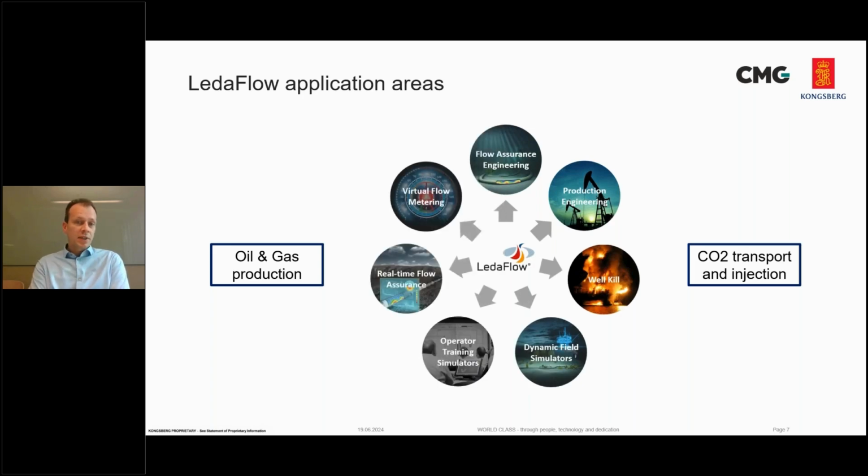To elaborate a bit on that, the application areas for LedaFlow include the classic flow assurance engineering. That's where it all originated as far as LedaFlow is concerned. But we've been doing production engineering for many, many years already. You can use LedaFlow for well kill analyses, where we first model the well blowout and then the subsequent kill operation using drilling mud. And you can use LedaFlow together with K-Spice as a coupled simulator for dynamic field simulators, operator training simulators, real-time flow assurance, and virtual flow metering. And you can do all of those things for oil and gas, as well as CO2 transport and injection.